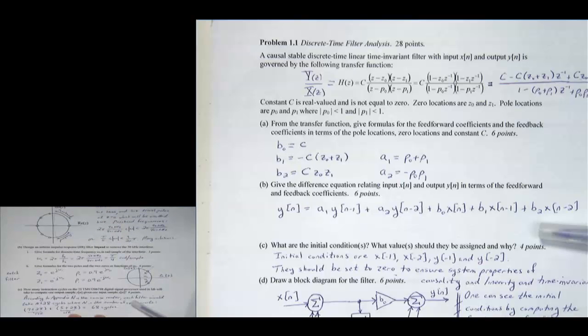This was in homework 3, question 3. Spent a lot of time on this particular issue for both biquads and for FIR filters. So there's a handout that I did record as part of lecture 6, part 4, when I recorded that lecture, and that's referring to Appendix N in the course reader. So this thing, it's assembly code that's sort of pseudocode, but it's n plus 28, where n is the number of coefficients in your filter. This works for either FIR or IIR, either one.